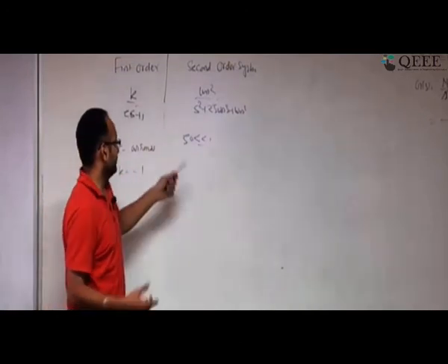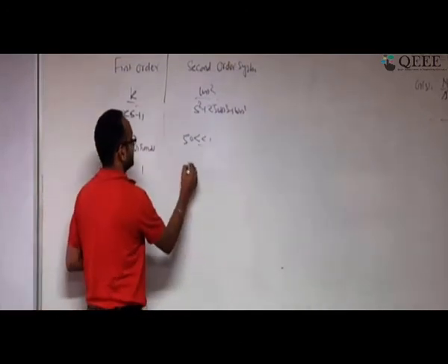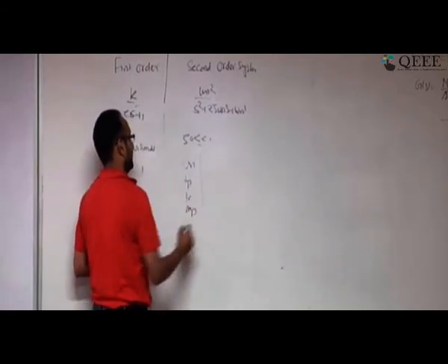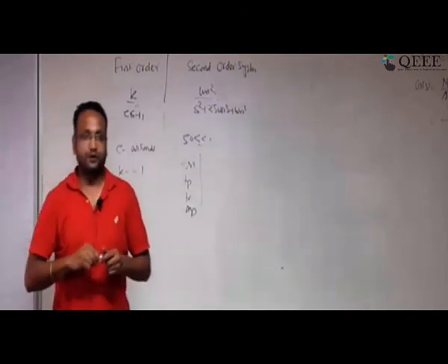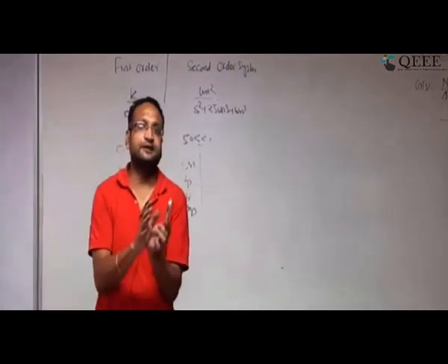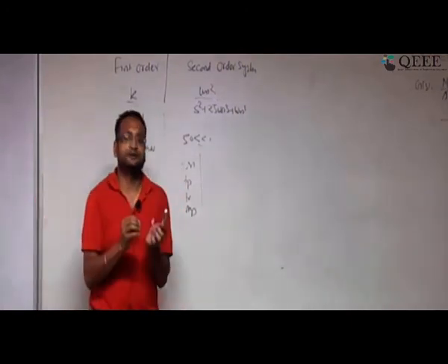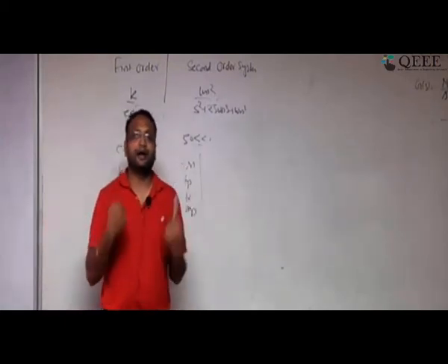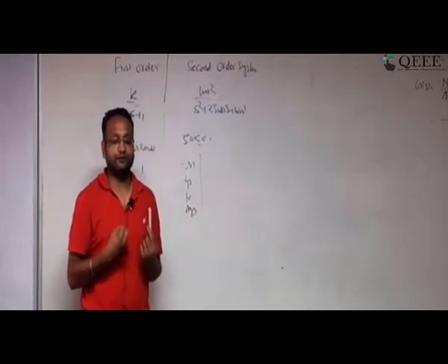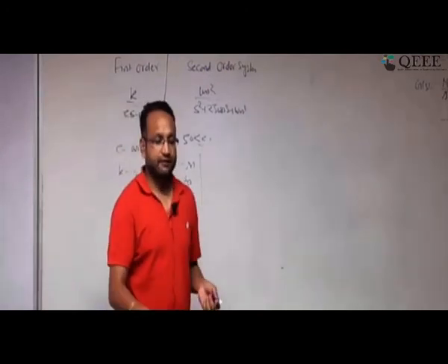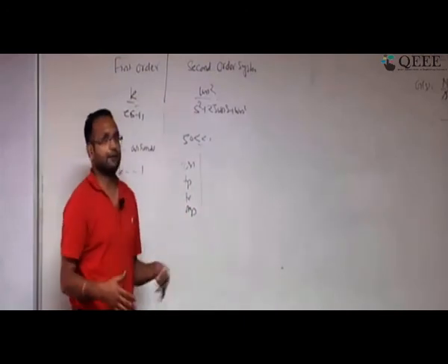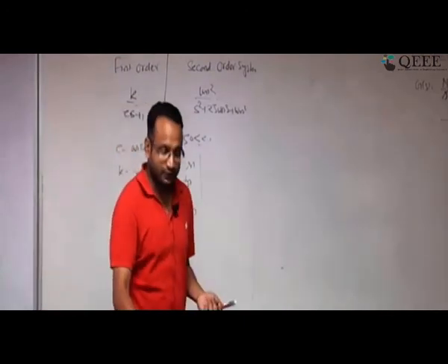So mostly we define some quantities: settling time, peak time, rise time, and overshoot, and we can look at all of these. What this module was about is to understand the response of a system defined using a first order relation and a second order relation. We are going to use these quantities extensively when we study the behavior of a system under the influence of different controllers.